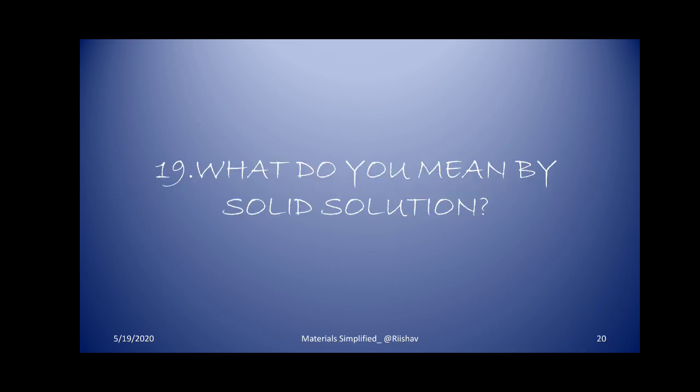Moving on. What do you mean by solid solution? Okay, so now we are entering phase diagrams. Solid solution: when 2 elements combine together to produce a single solid phase, we call it solid solution. It's something like solid ka solution, they exist in a single solid phase. They are stable in a single solid phase in simpler terms. There are 2 types of solid solution we'll study later, interstitial solid solution and substitutional solid solution. If asked types of solid solution, you can answer 2 types, substitutional and interstitial.